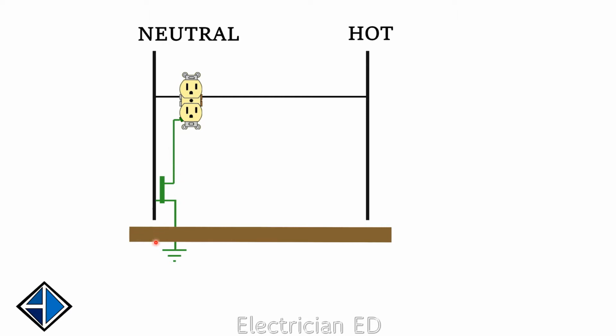Some things that I didn't show in this that I kind of wish I would have drawn in is there's another grounding connection in every system, and that happens at the transformer. So outside your residence, there will either be a transformer up on a pole or on a pedestal of some sort. And the center tap on a single phase of that transformer, secondary side, will be bonded to the earth.